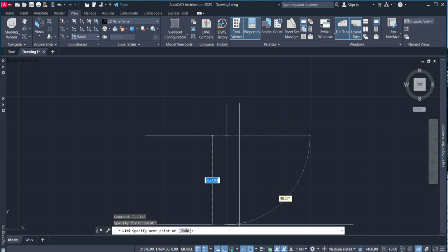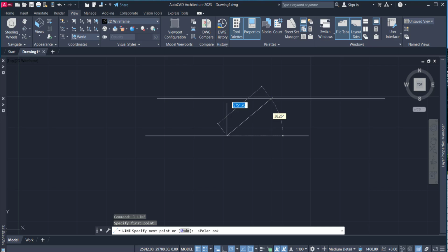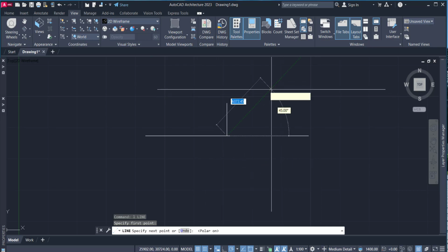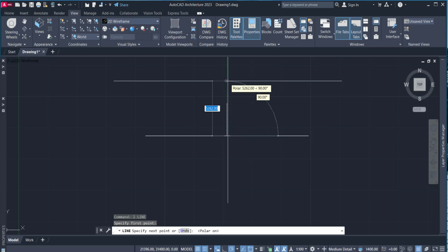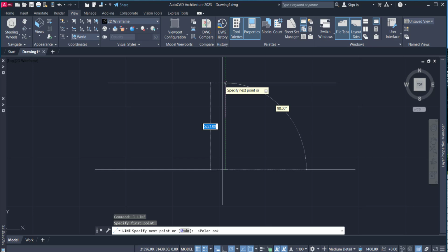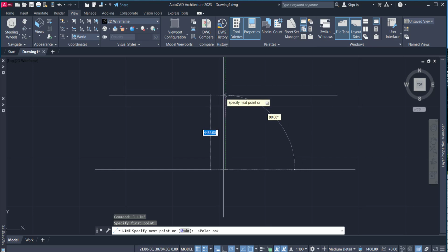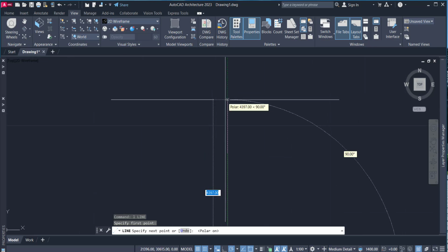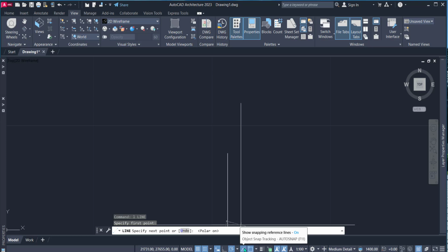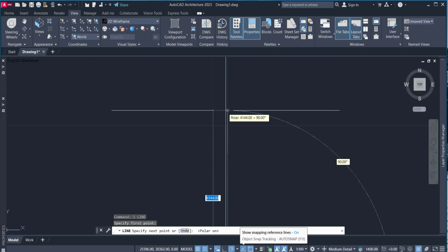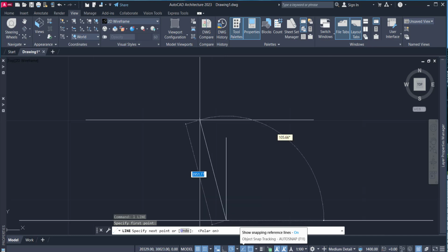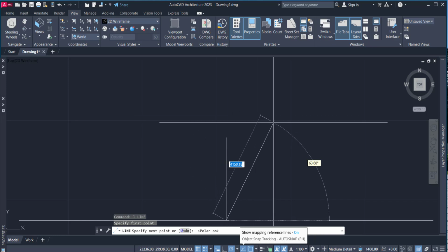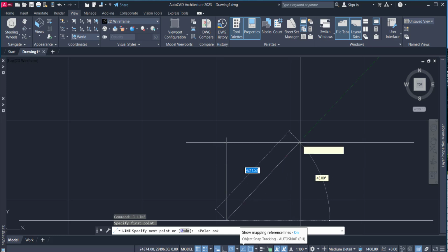Now, when you move to this area, you can have the access to rotate your line to any angle of your choice. So, it can also give you the chance to draw a 90 degrees line. The tracking is showing here as a green line, that is the object snap tracking. So when your line is straight, the green line will appear. Then you have the access to type in your dimension over here. Then your degrees angle is also moving to this right side.